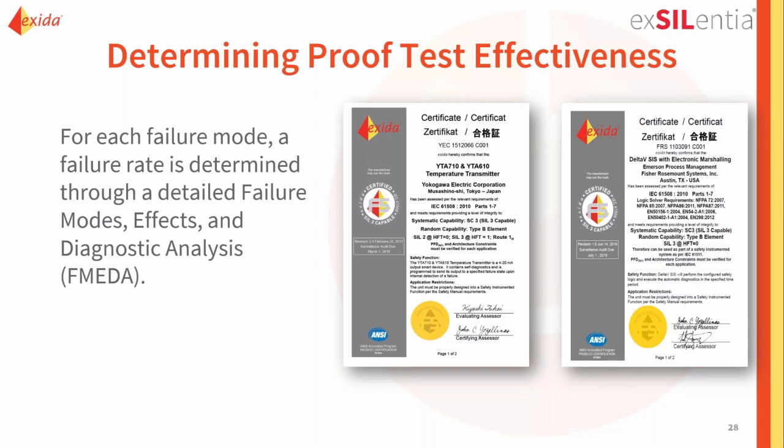Typically, if I look at the certification process that we at exida tend to do, we perform a failure mode effect and diagnostic analysis. And when we perform that analysis, we have a very detailed overview of all the different failure mechanisms in a device, and we can see, if we perform a certain test, what the failures are that will be detected or revealed by that test. So we can very accurately predict what that proof test coverage is.